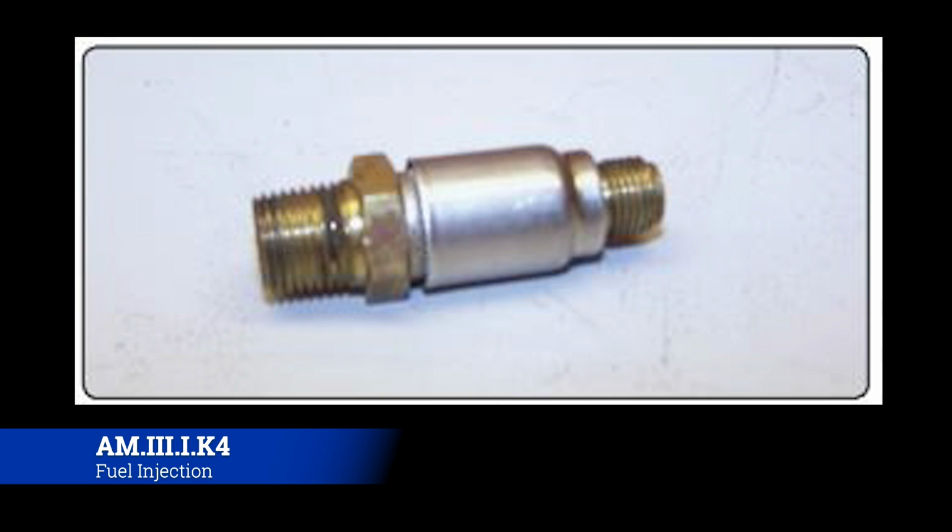Okay, so this is the end of the line for your fuel: the fuel nozzle assembly that's going to come at the very end of it, and this is what actually is going to finally atomize the fuel and spray it into the cylinder. Now these will get, like I said, pulled off every annual and cleaned. The big thing with these is that they are typically very soft, and so you don't want to tear them up. They are also expensive to replace.